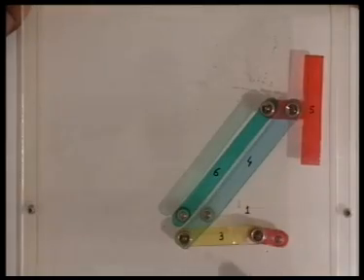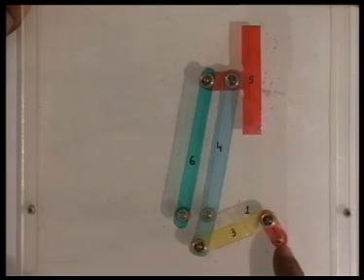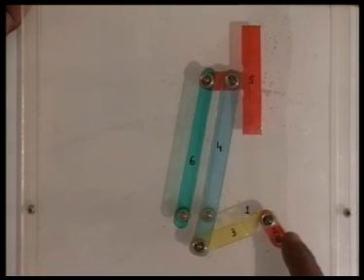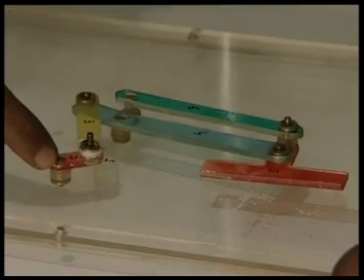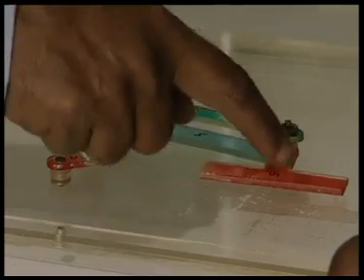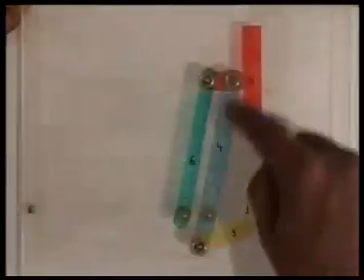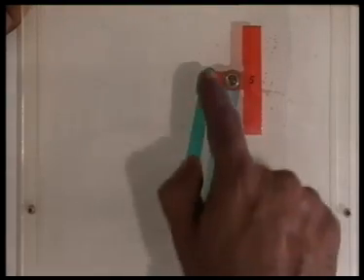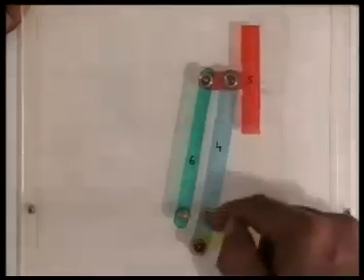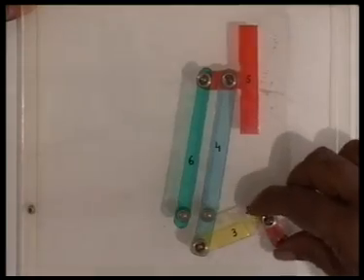We demonstrate the same wiper mechanism that we have just now studied. This is the same wiper mechanism consisting of a crank-rocker consisting of link 2, link 3 and link 4. O2 and O4 are the two fixed hinges. And there is another parallelogram linkage starting from here, link 4, link 5 and link 6. This link length is the same as this link length and this link length is the same as this link length. So, it is a parallelogram, and we should note, because it is a parallelogram linkage, the coupler remains always parallel to itself, it never changes its orientation.